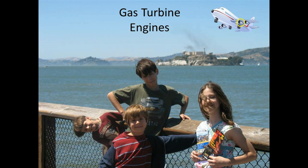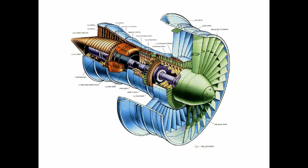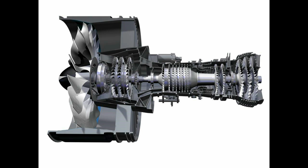Most passenger aircraft use turbofan gas turbine engines, which consist of an axial dual-spool gas turbine engine that burns kerosene as fuel. Excluding the turbofan, the air is directed through variable inlet guide vanes which direct the air at a certain angle into the first stage compressor blades.